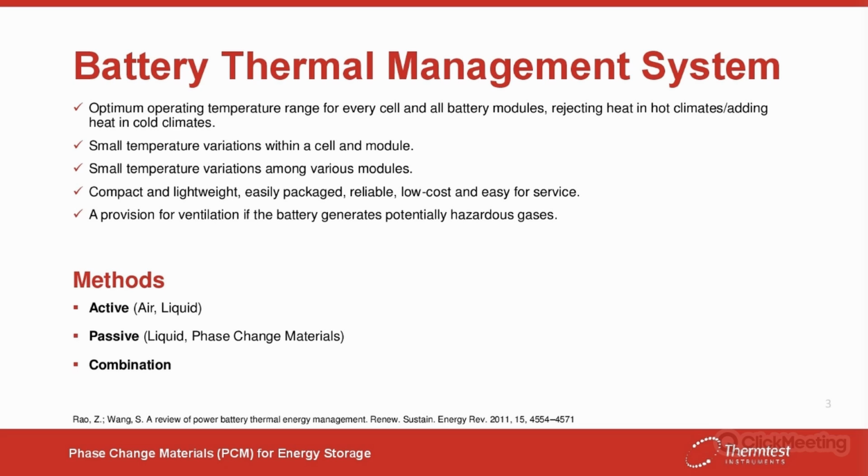Additionally, we need to have small temperature variations within the cells and the module, but also among the different modules of the battery system. It needs to have low weight and be easy to pack, to be reliable and low cost, and of course to be easy to service.